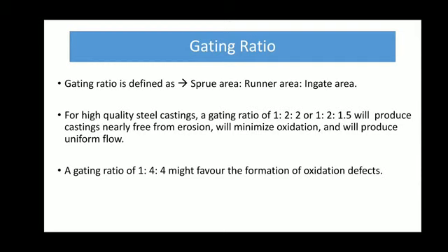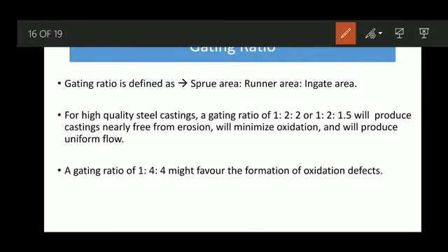And what is the meaning of gating ratio? It is sprue area to runner area to ingate area. Don't get intimidated when it is sometimes asked in competitive exams. Don't write sprue volume by runner volume by ingate volume. It is not the volume ratio. It is sprue area to runner area to ingate area. Don't mix them up. That is what you should remember.